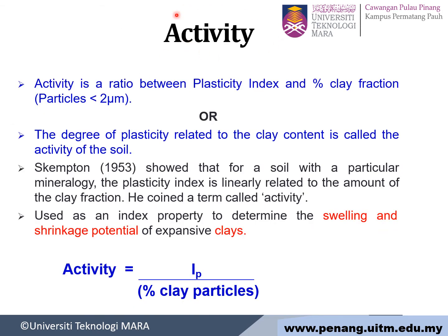Now we go for the equation for activity. Activity is the ratio between plasticity index and the percentage of clay fraction, for clay with particle size less than 2 μm. Okay, the degree of plasticity related to the clay content is called the activity of the soil.